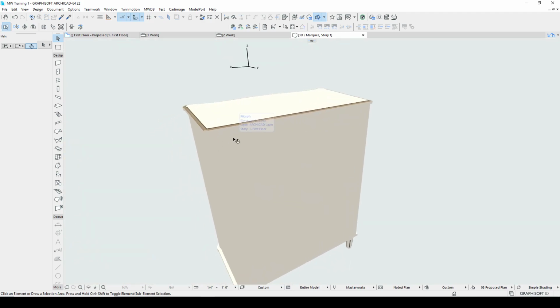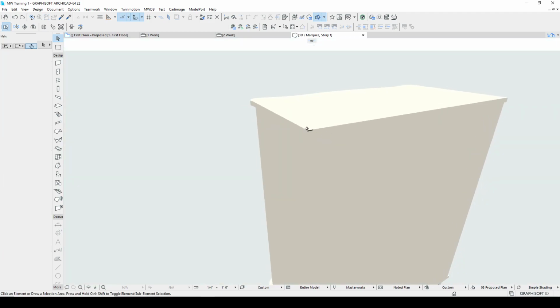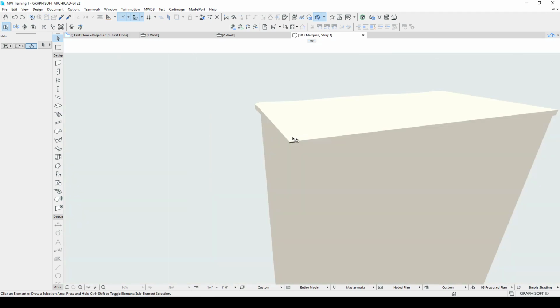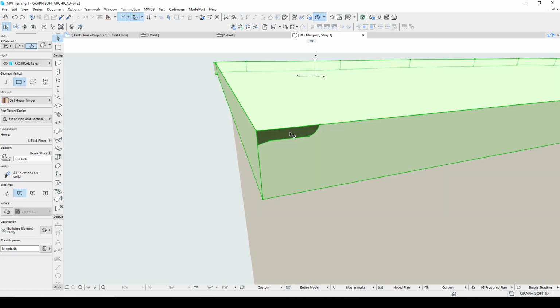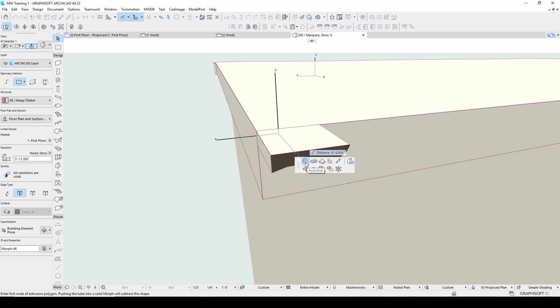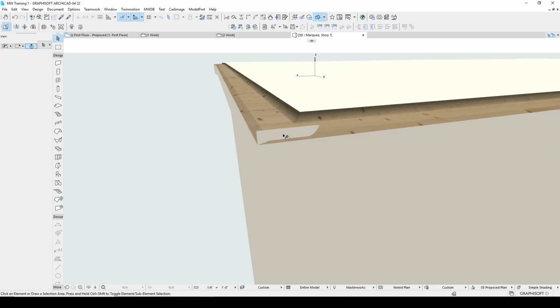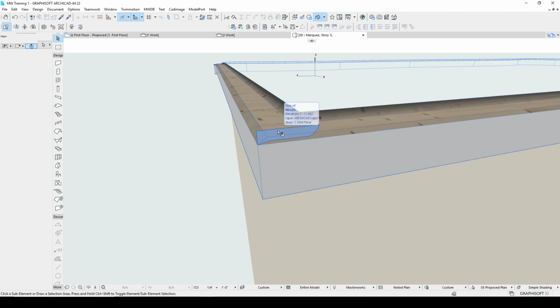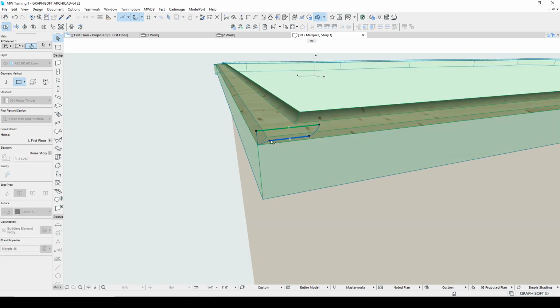So let's look at that one more time. I'm going to undo it just because I know it's a little confusing. So once you get that little planar cut on the back, you could do one on the bottom, of course. So I'm going to, it's unioned. It has to be unioned. I push the tube button, and I hit spacebar to select the top surface of the morph, and it sweeps all the way around. I use the shift control to delete the original cutter. Looks like I'm going to have to delete the line work as well.